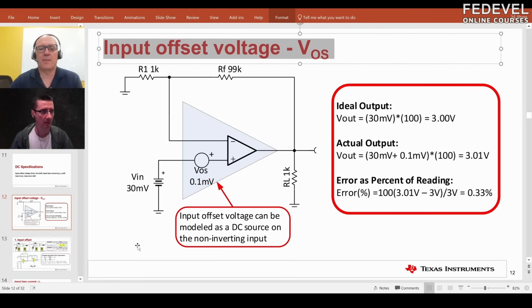And the other downside to calibration is that it's costly, because to calibrate, you have to actually apply a test signal, and apply a different test signal, and then you have to make measurements, and then you have to store things in an EEPROM or in your microcontroller. So it takes extra effort, and it adds cost. Sometimes people will just try to pick the optimal signal chain and make sure the offset is as small as possible, and in other cases they will optimize by using calibration.